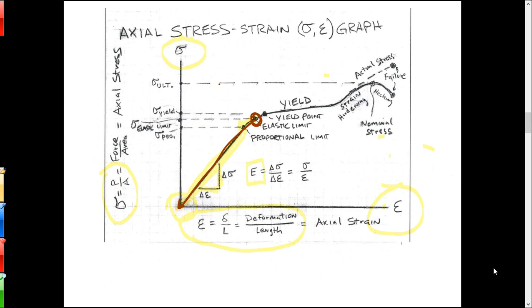Now, what's happening here is you start to stretch these bonds out. There's a point when you just start ripping them apart. You've stretched them too far. It's like you've totally deformed these springs, and all of a sudden the material will just stretch out like taffy, you know. If you pull on it, like you ever blow on a balloon where it's kind of hard, and then all of a sudden, bang, it just pops right up. You know that feeling? That's called yielding. This is that plastic area. So for very little extra stress, you'll get quite a lot of elongation. That's what happens next. It really resists very hard, then all of a sudden it'll just give up and it'll really stretch out.